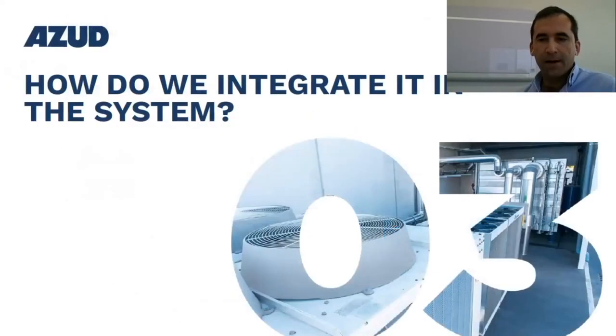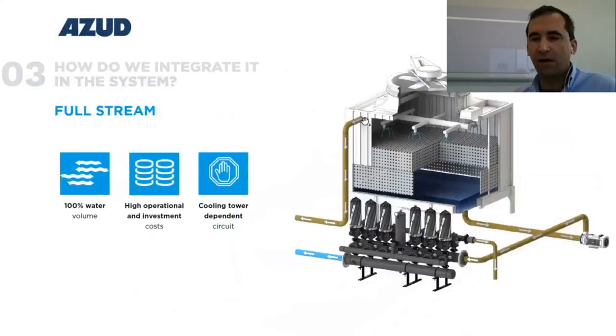So, how do we install a filtration system? We have two options. The first one is full stream. The full flow filtration uses a filter installed after the cooling tower on the discharge side of the pump. So the filter continuously filters all the recirculating water in the system, and the filter must be sized to handle the complete flow rate. So as it has to filter the complete flow rate of the circuit, you will need a larger filter, so your capital expenses will be higher.